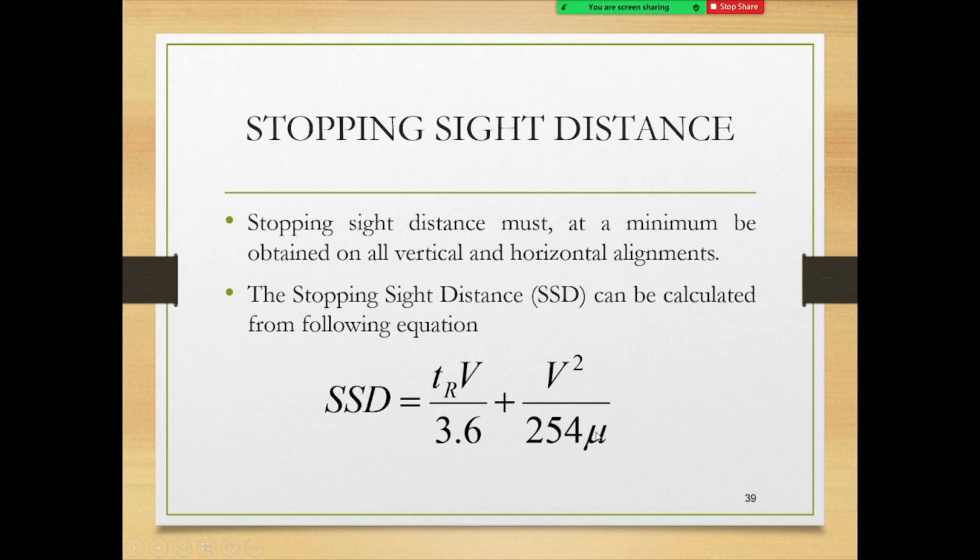There are two friction factors. Now when it comes to the super elevation, we discuss about what? Side friction factor. Side friction factor means across the road. Please note down, side friction factor is across the road. Lateral friction factor is along the road. Did I say across the curve? No, across the road. Across the road. And this is along the road.